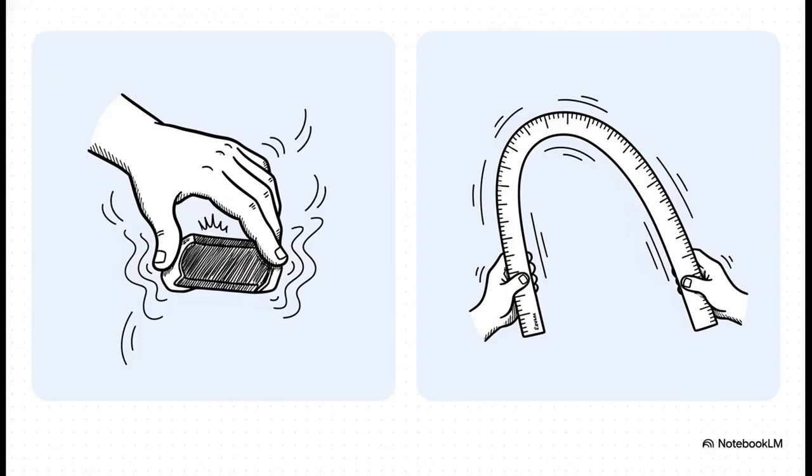That's crushing. Short columns have a huge cross-section compared to their height, and they fail simply because the material itself just gives up. But if you take a long, flimsy plastic ruler and push down on the ends, it immediately bows outward in the middle. That outward bending is called buckling, and it's exactly what happens to long, slender columns.